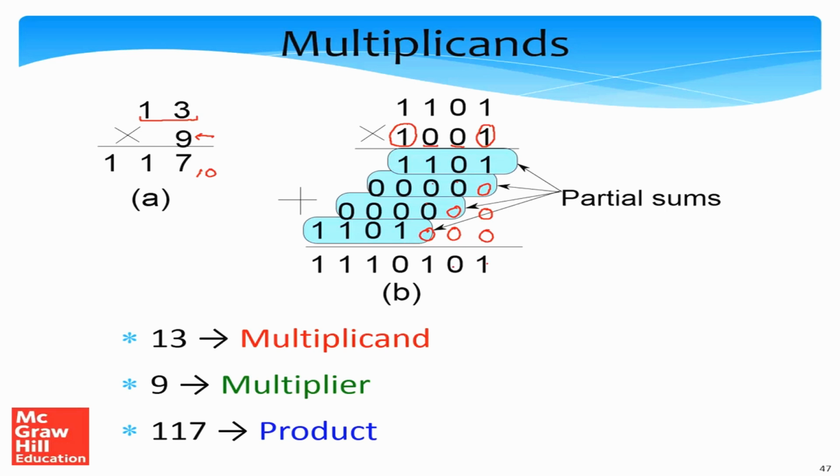At this point we get 0. We add 1 with 3 zeros, so we again get a 1. Then 1 plus 1 gives a 0, and there's a carry of 1. So 1 plus 0 becomes 1. Then 0 plus 1 is 1, and again we have 1 here, so this is what we have.